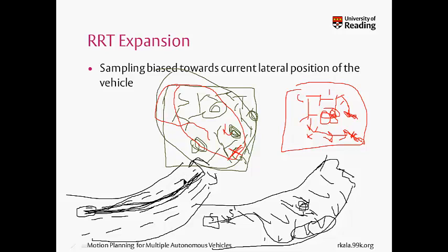So I'll generate more samples in this region and very few samples in this region, and that's why my RRT will be mostly around this region, and only if an obstacle is found such that a high amount of steering is mandatorily required will these areas be explored. So what I've done is biased my RRT expansion towards this narrow region. Now it plays a very good role in computational boost. Effectively only this part of the road is to be explored, given there is no obstacle.